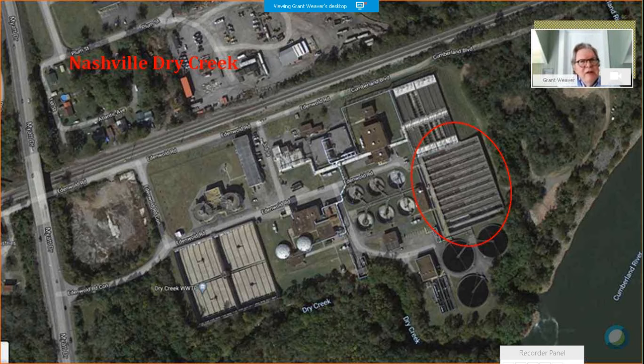And that's really a benefit of, not universal, but in most cases, a benefit of changing your operations to one of these air on, air off. Oh, I didn't mention that, north. In the aeration tank for nitrogen removal, they're cycling that air on and off for an hour or 2 at a time on, hour or 2 off. My apologies for not mentioning that.